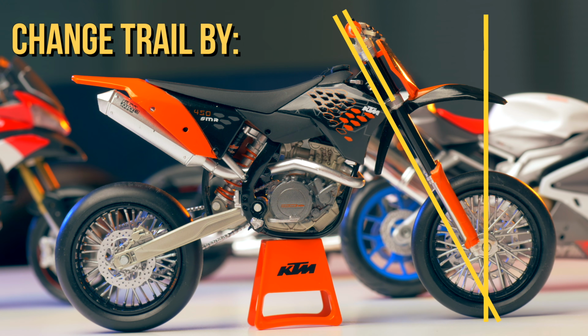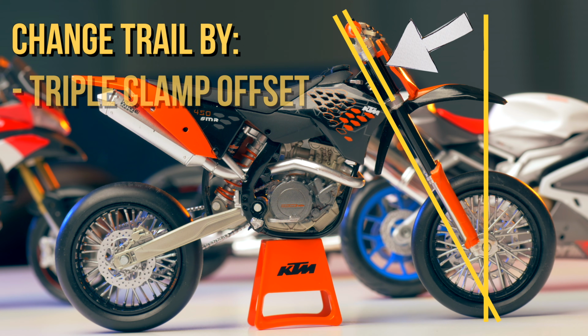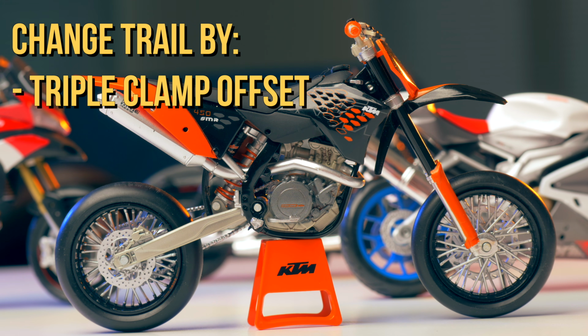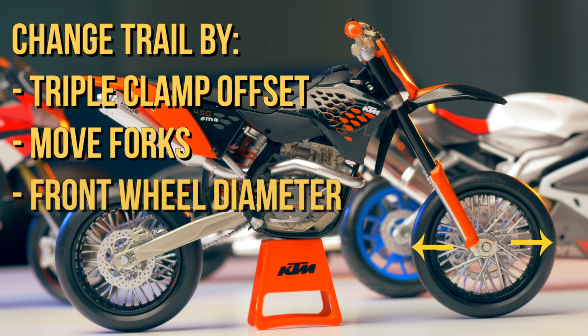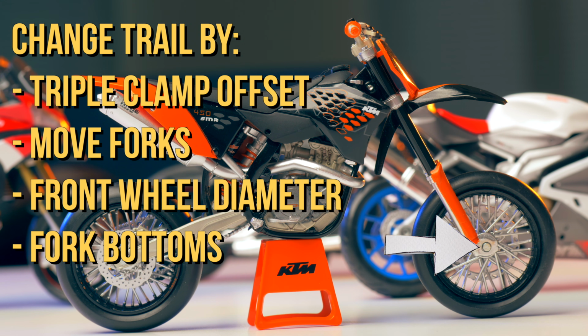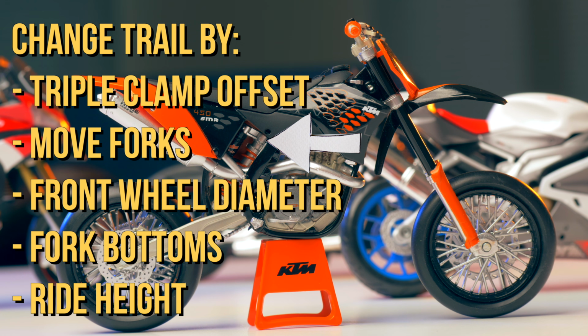The amount of trail you have can be adjusted by changing the triple clamp offset. Longer offset equals more trail and vice versa. Moving the fork tubes in the triple clamps, moving them upwards will result in less trail and vice versa. Changing the front wheel diameter: a larger wheel will provide more trail and vice versa. Adjusting the fork bottoms to move the axle back or forward: moving the axle forward will result in more trail and vice versa. Lastly, you can adjust the ride height in the rear. Lowering it will increase the rake, which provides more trail.